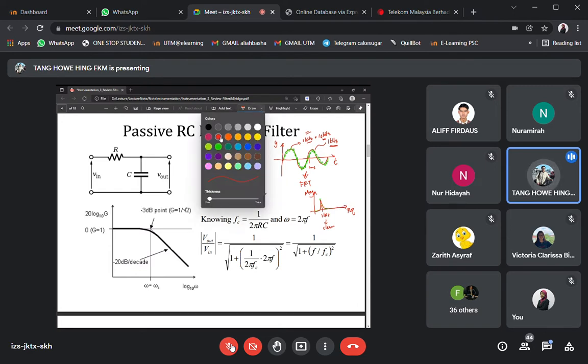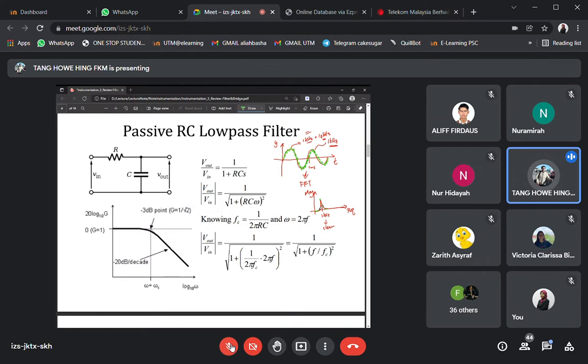Whereas for the green color, the spectral plot will be looking something as this, and then there will be other spikes over here. And because this noise signal is having a frequency of 10 kilohertz, by the FFT, there will be two spikes for this noise.